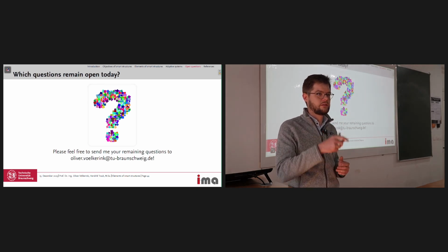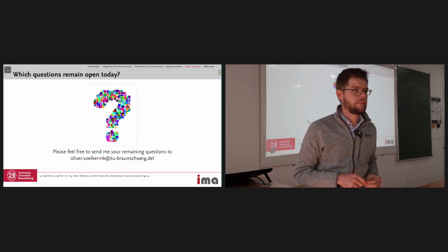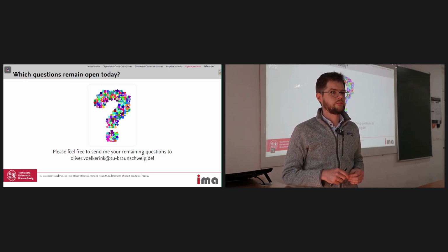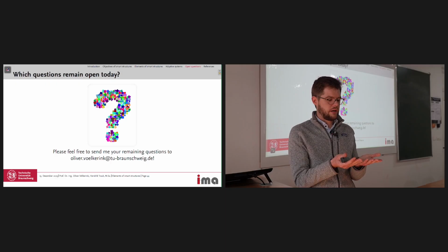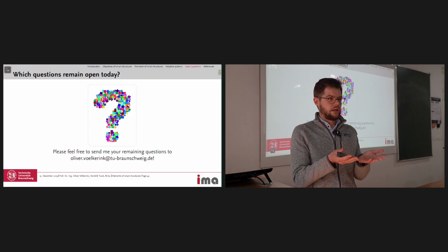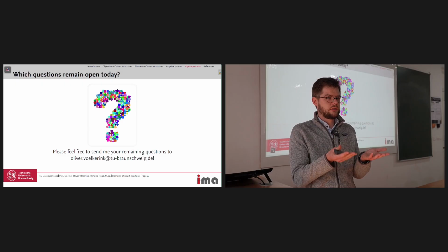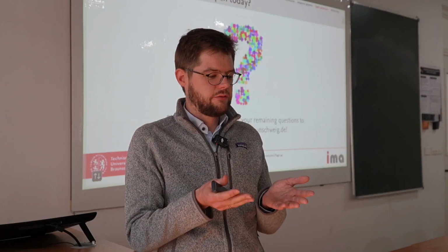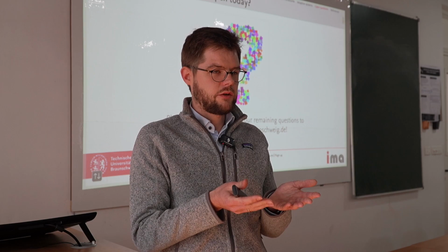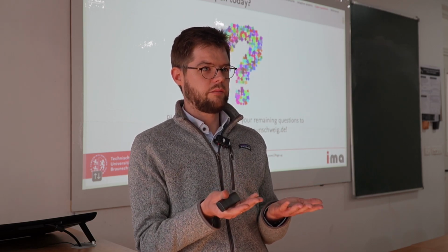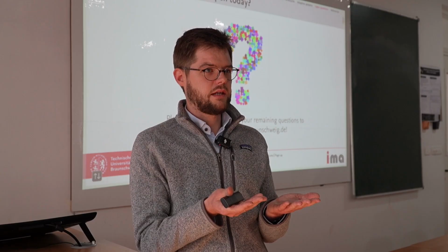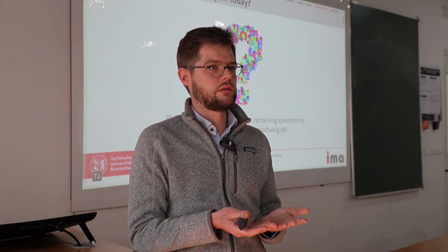So the reflector parabolic shape, yeah. Temperature changes. So how with this actuator can we suppress the malfunction? Yeah. So the idea is if you have the one-sided thermal loading, then the reflector deforms a bit and it loses its reflector focus, or the signal transmission is not that good like in the previously defined state. And with the integrated actuators, you deform the reflector back in the wanted state so that you have good signal transmission.